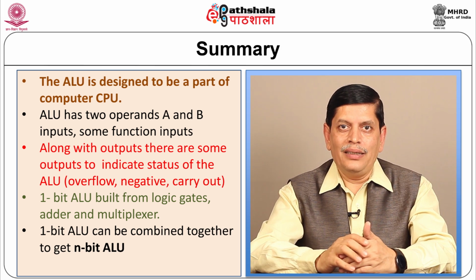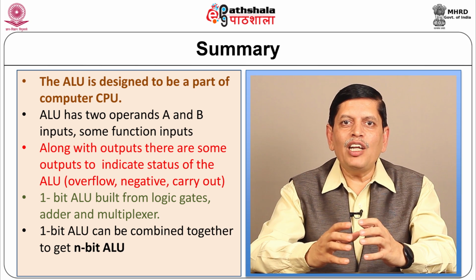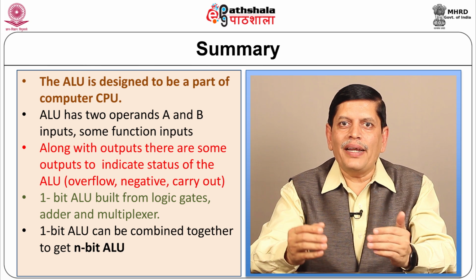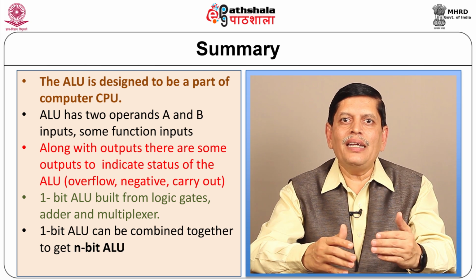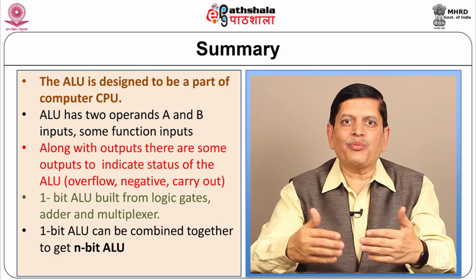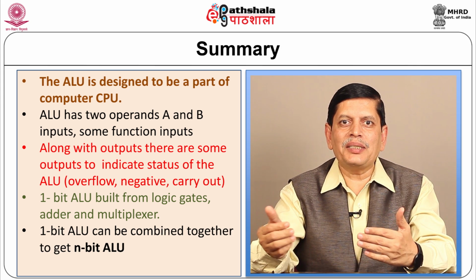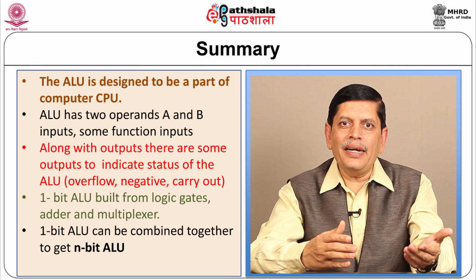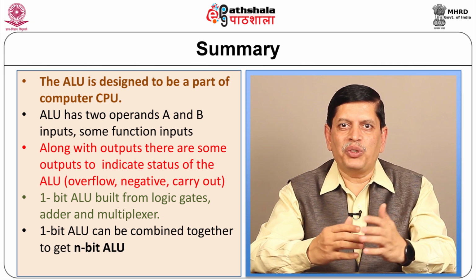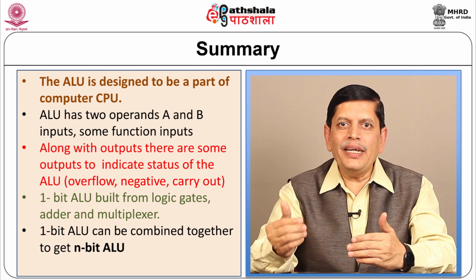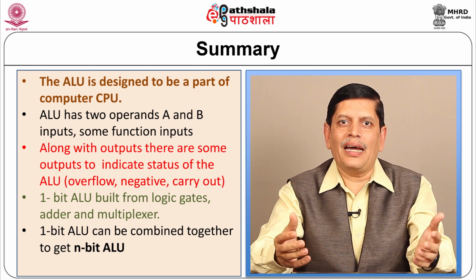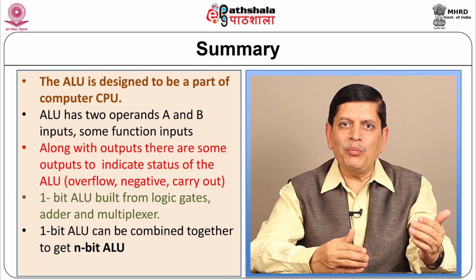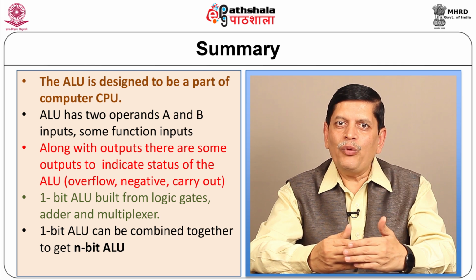In addition to that, we have studied a commercially available IC, TTL IC specifically 74181, which basically performs 16 arithmetic operations and similar 16 logical operations. The inputs could be inverted or uncomplemented inputs, and the outputs that we get could be selected by the select lines. So, just to sum up, we have started with the simple 1-bit design and we ended with a simple standard ALU IC.